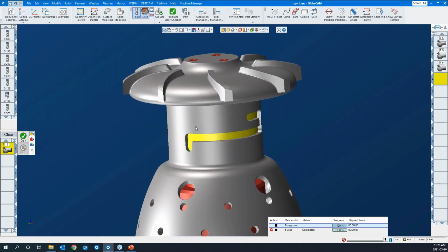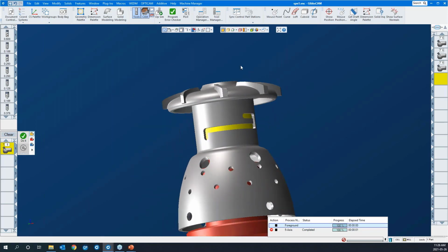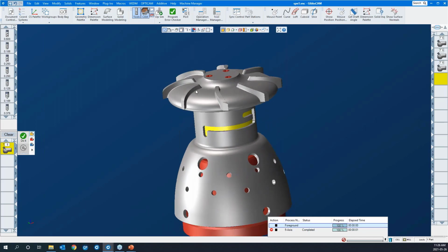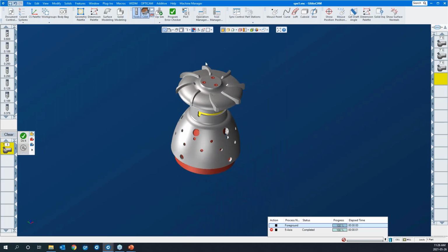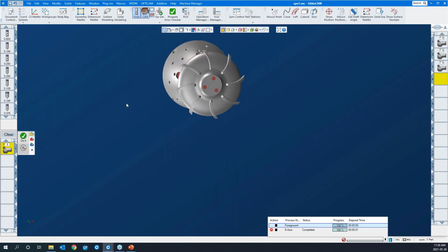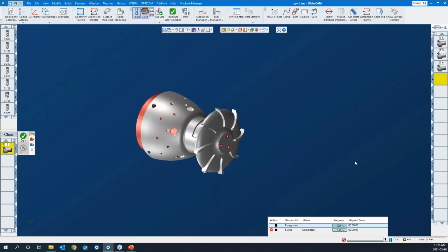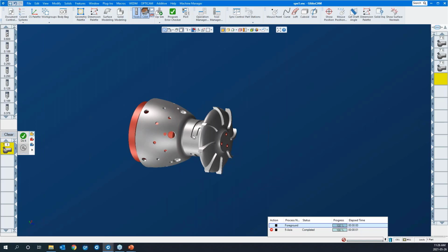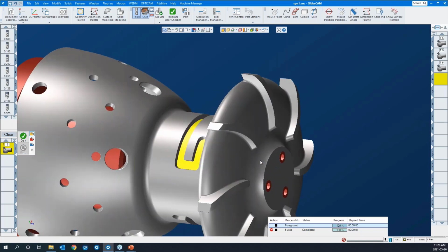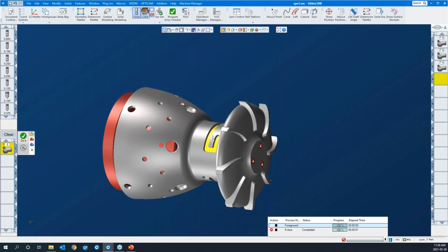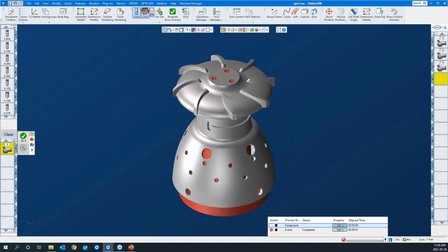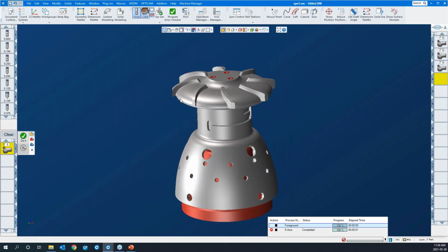We're going to look at this radial slot here. This is a 5-axis machine, has full 5-axis on it. However, if we were to rotate the part along the trunnion axis 90 degrees and access this slot, in a sense, we're now on a 4-axis mill. Although this is 5-axis, this certainly can be done on your 5-axis or your 4-axis vertical mill or horizontal for that matter.